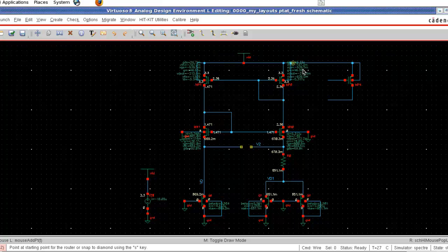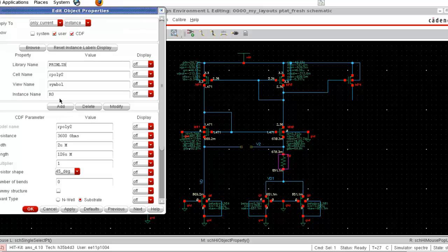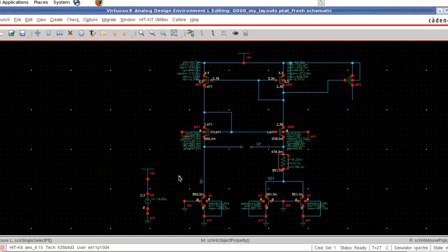So supply is connected. We need equal gate voltages. So I want to connect this gate to this gate. So we already have this voltage here. Now all the PMOS gates are connected. All the PMOS gates will have equal voltage. In our discussion we called this resistor as R1. So here I am calling it as R1, and we have another resistor and copying the same resistor R2.